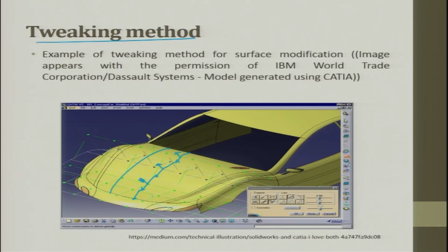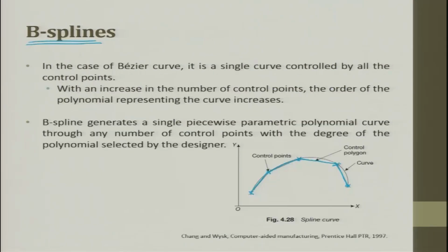Okay. So, it will look as though it is smooth, but when you watch very closely you can see several small facets or curve structures, because the curve has been discretized into several small control points. So, this is what is talked about in B-spline. You have control points and you have control polygons.